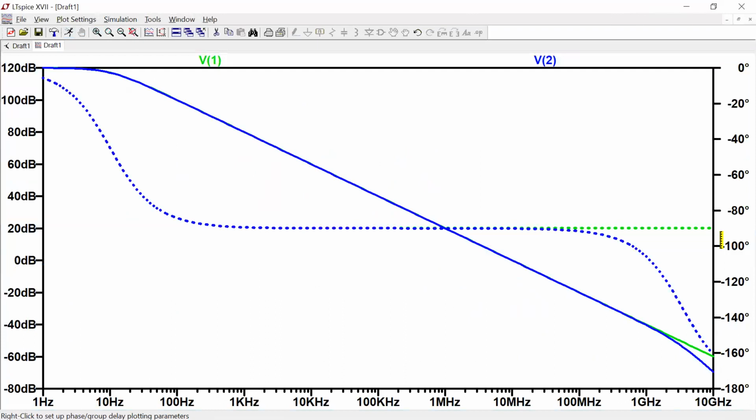I think I used a gain bandwidth of 1 megahertz instead of 10 for those other examples. So you can see level 1 is 1 pole because the phase goes from 0 to minus 90. The level 2, you can actually see it's behaving like a second order because here's minus 20 dB. Then at this point, it's minus 40 dB, and the phase is headed towards 180. I just have to go farther.